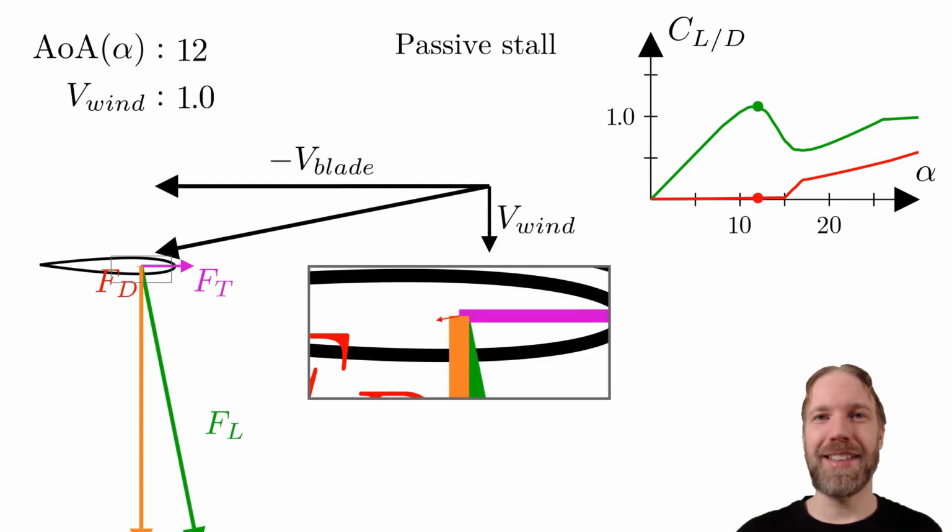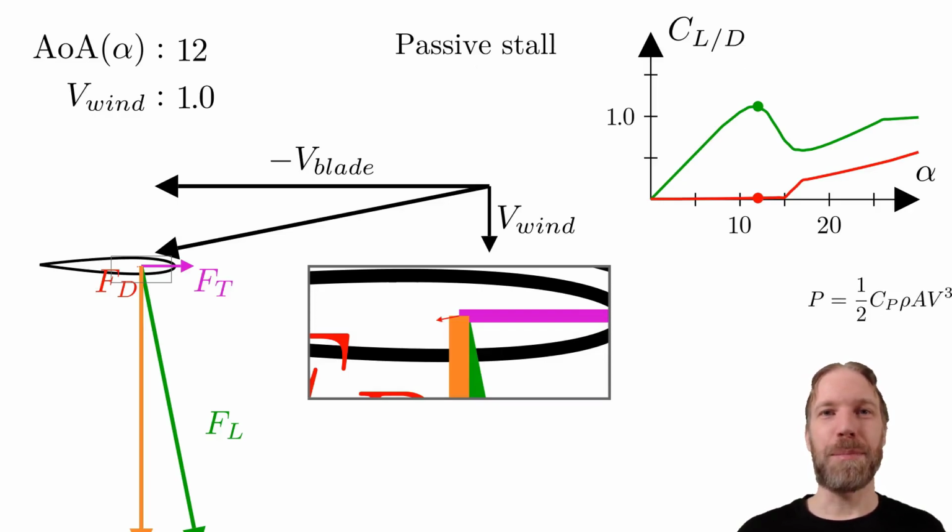If anyone thinks it is strange that it's quadratic and not cubic, as the power increases with the cube of the wind speed, and the power is the tangential force multiplied by the constant rotational speed, you need to include that for a turbine the thrust force will reduce the flow speed through the turbine, as we saw in the Betz theory derivation. Hence, later when we include the momentum theory, we will see the cubic growth.